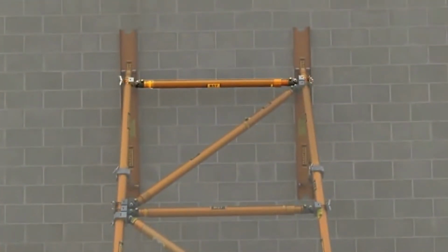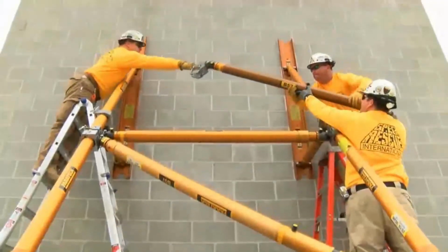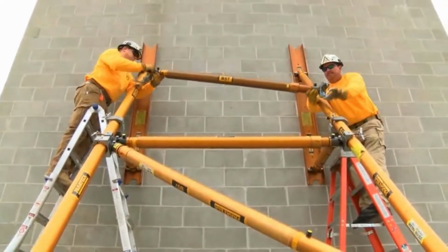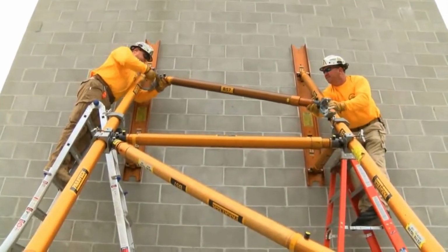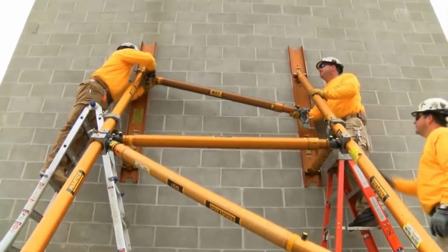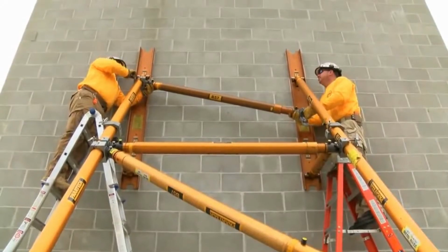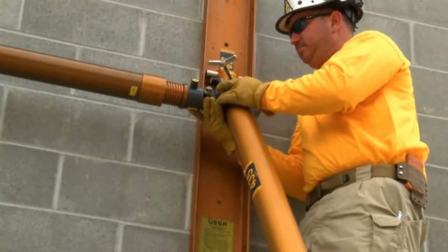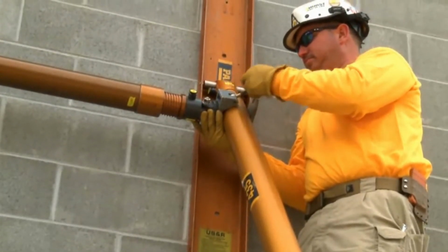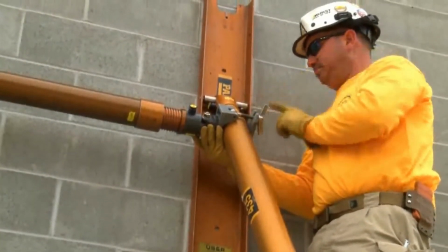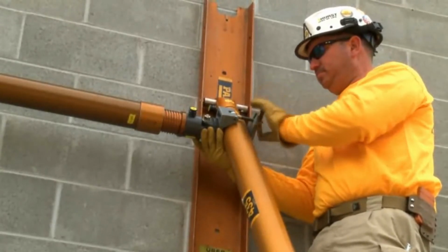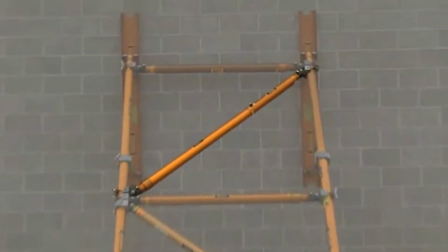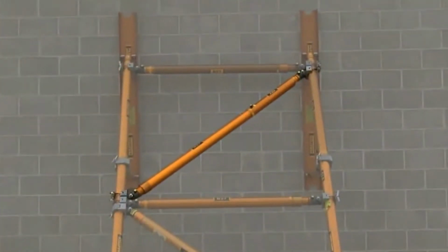Next, attach the top lateral brace. Take the clamp and clevis, and at the top of the strut there is a shoulder. Slide the brace up. Again, we're attaching the non-movable end first. On the left-hand side, notice it is attached even with the shoulder of the actual strut. Take the adjustable end and slide it up, opening the jaws to get it to fit over the strut they're going to, up to the strut shoulder, the top shoulder of the clamp and clevis. Match it to the shoulder of the strut and hand tighten. Once complete, we are now ready for the next diagonal brace.